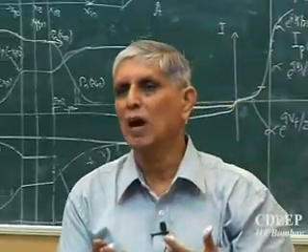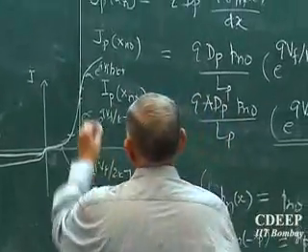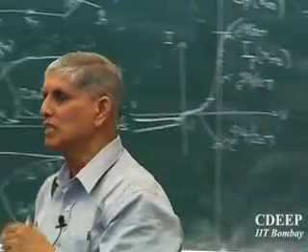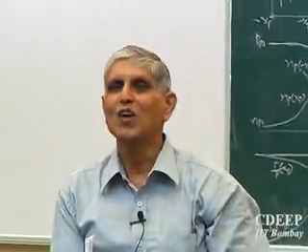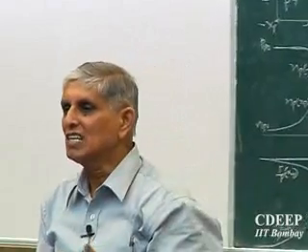Now why does this slope change? In most cases of the circuit, you will never reach this value, or you will attempt to, but there is something in the circuit. How do you limit the current? Oh, I already said the word. How do you limit a current in a circuit? Current is essentially V by R. You have a circuit resistance R, plus you add your resistance, that is R plus R dash. Now even if R goes to 0, V by R dash will give a limited current. This is called a limiter.